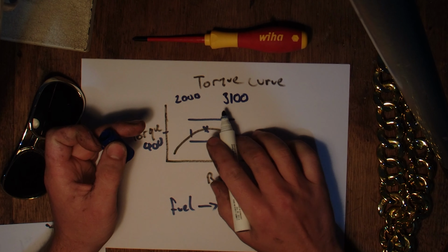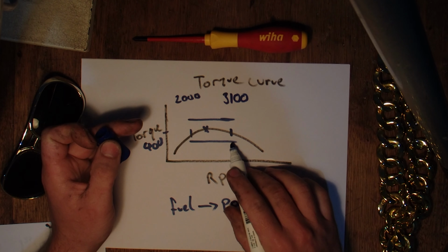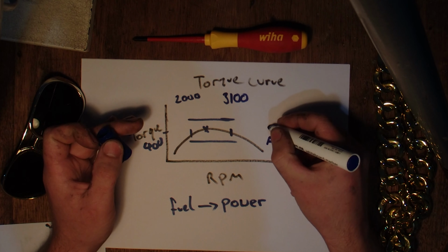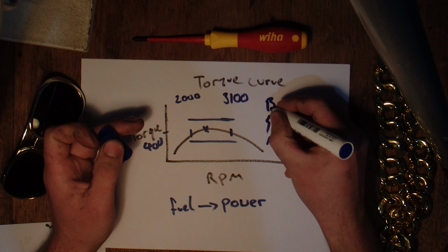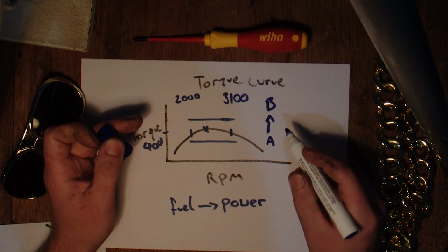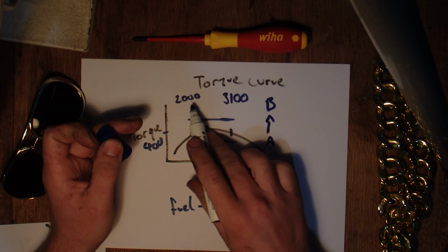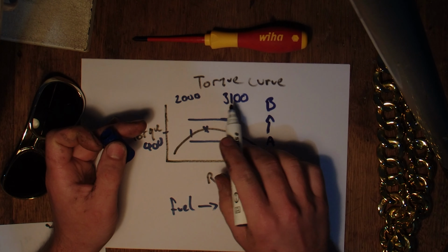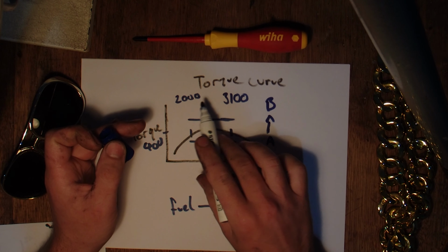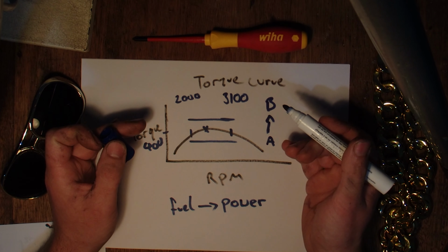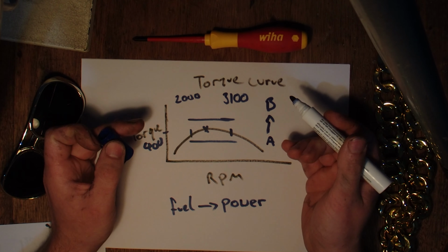Because if I'm spinning more than that, then I'm going to be burning more petrol because I'm losing efficiency. So for me to get from A to B the most efficient way possible, using the minimum amount of petrol, or diesel, whatever your fuel source happens to be, I want to be shifting between these points and maintaining the engine RPM between these points when I'm trying to get power out of the engine.